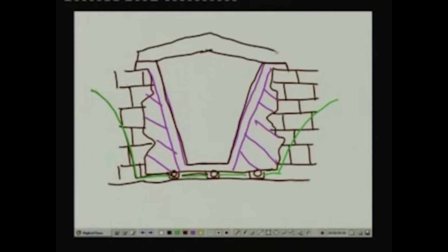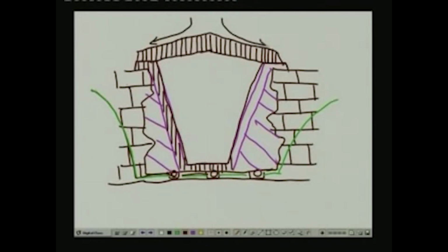and on top of the waste material was another cover comprised of very fine grained clay soil, which is impervious for all practical purposes, and the top of the clay soil was sculpted to provide a surface slope so that any water due to rain or snowfall or whatever can flow away before it gets a chance of entering the waste placed within the landfill.